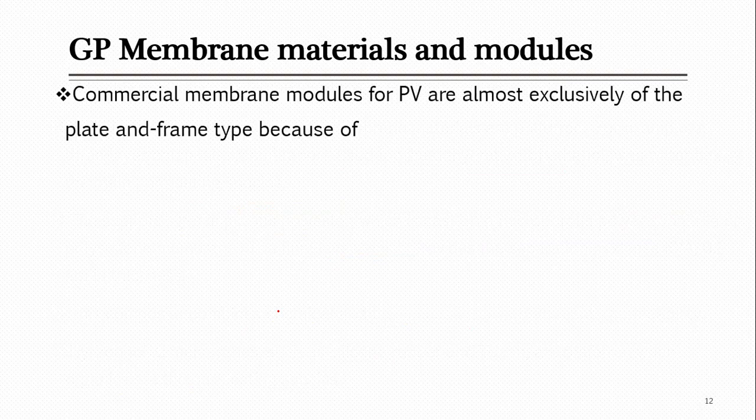Regarding modules, mostly commercial membrane modules for this pervaporation. Sorry, this is PV, pervaporation. This is not like GP, this is not gas permeation, it is pervaporation. So for pervaporation, mostly plate and frame type modules are used, and there are certain reasons for this module usage.